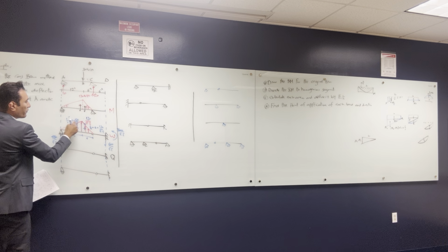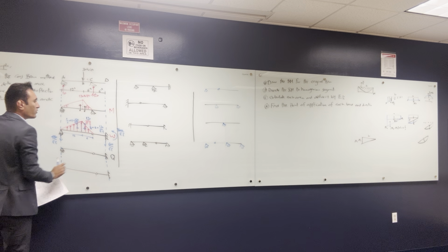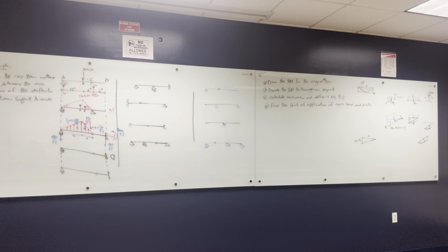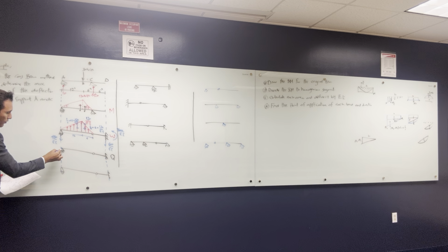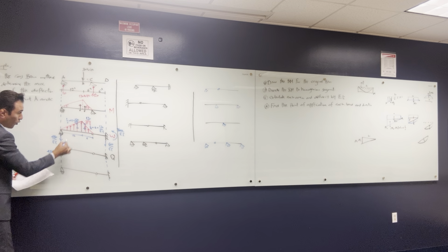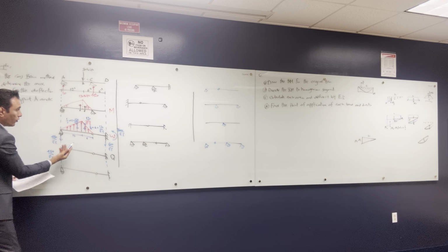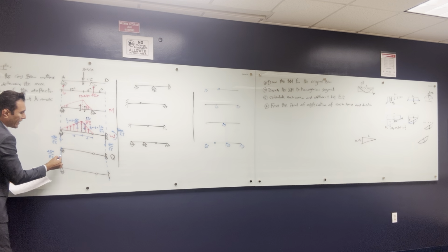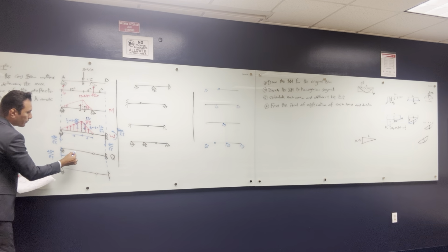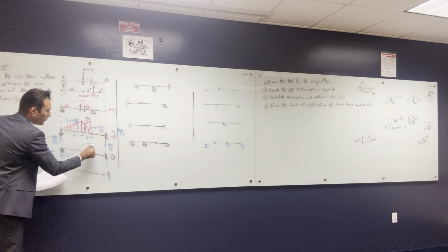And the summation of this load should be 1080 over EI once you finalize this. So you got reactions. Right now you can draw the shear force diagram. To draw the shear force diagram for this load, it's gonna be something like this. You're gonna go down 480 over EI, and this is gonna go up because you have a load going up, it's taking you up, and it's second degree, so it's gonna be something like this until you come here.